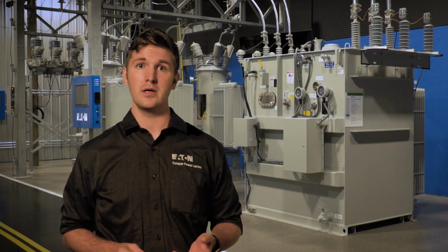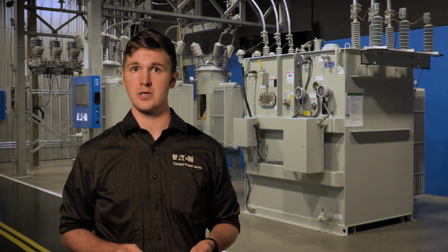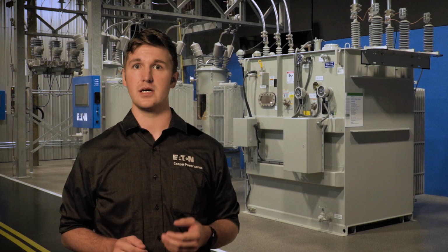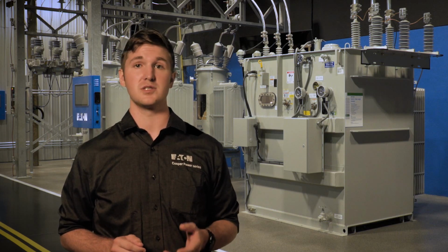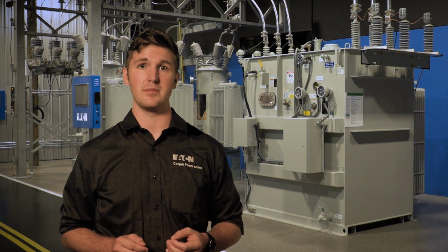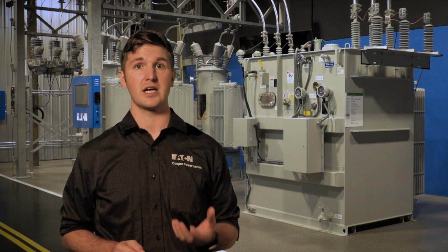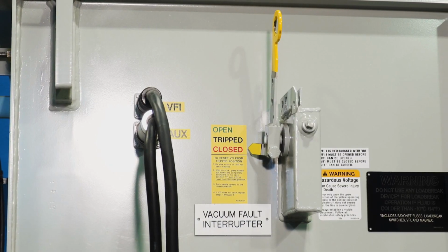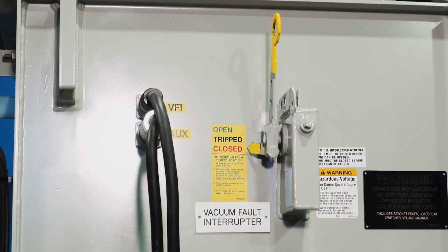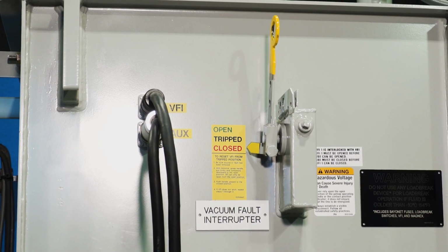Consequently, on a loop, when a downstream fault occurs, the VFI breaker trips, isolates the fault, leaving the transformer load uninterrupted. In specialty applications, 2 VFIs can be used in one transformer to protect both the VFI coil path and the loop path. The VFI mechanism in a VFI transformer has a hot stick operable handle located on the faceplate of the transformer, with operating mechanisms configured for ganged 3-phase operation.